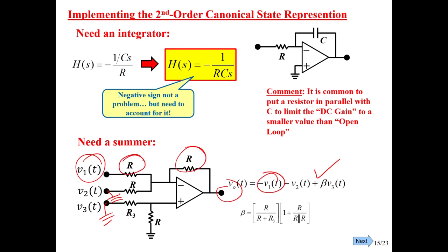Now you might be saying, wait, why doesn't this do a voltage divider so that you get a half of R? Well, with this grounded, there's no current flowing here, so there's no current through those resistors. So this is actually effectively at ground, and this then is effectively at ground. So if I ground this and this is grounded, this resistor is out of the picture. So when I first looked at this a long time ago, that bothered me, and then I figured that out. Well, I read about it in a book, I'm sure.